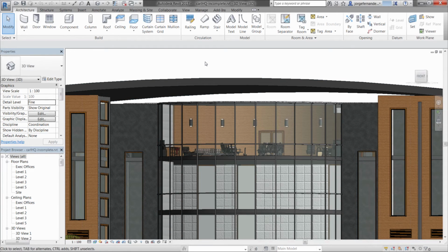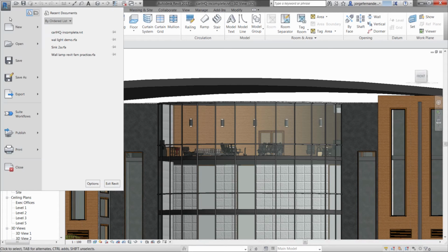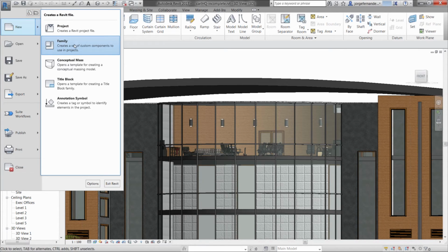So in Revit now, I'm not just going to go ahead and insert it here because it doesn't know to attach to a wall. I would basically be bringing it into a space. So what we need to do is create our own Revit family. You could just bring it into 3D space, right? But it makes it a little more difficult. Let's make it attached to a wall. In order to do that, I'll come over here to New and say Family.